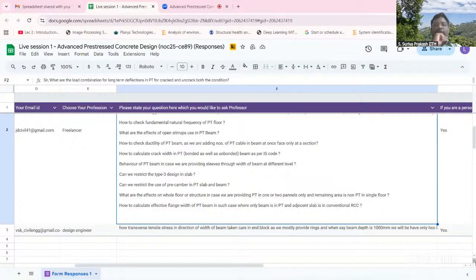The code typically gives you a minimum that you should have, which is 3. If this beam system is part of a seismic system, in zone 4 or zone 5 in India, we need to have a minimum curvature ductility of 3, right? So this way we can measure the cross-section ductility. But if you want member level ductility, then you have to do a number of these cross-section analyses and find out the load deflection behavior of the beam. From the load deflection behavior, we can measure the ductility.